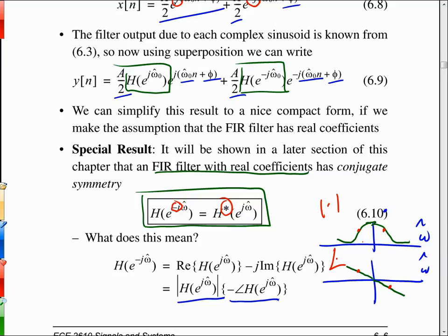And in terms of the continuous time domain, which you'll start studying next semester in 2205, the real coefficients do hold because we use R, L, and C values in an analog circuit that end up corresponding to filter coefficients that are purely real, in the sense of the differential equation that would result. Some of you are taking differential equations now, some of you will get to it later, but that's one of the reasons why we can do discrete time domain and not have to be so concerned about the solving business, because difference equations are easier to solve and work with than differential equations. But there is a direct analogy between the FIR filter coefficients and lumped element circuits, let's say.